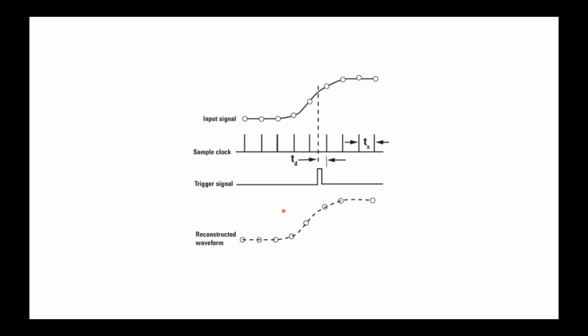So before we can talk about how this subsampling oscilloscope works, let's just go over how a regular, traditional, real-time sampling oscilloscope operates. Now I'm sure you're familiar with this and you've seen this before. Imagine you have an input signal and you're interested in digitizing it with sufficient signal integrity and sufficient bandwidth to have a good reconstruction in the digital domain. And in the digital domain, then you can either display it on the oscilloscope screen or actually perform FFTs and DFTs and get spectral content or do some DSP on it.